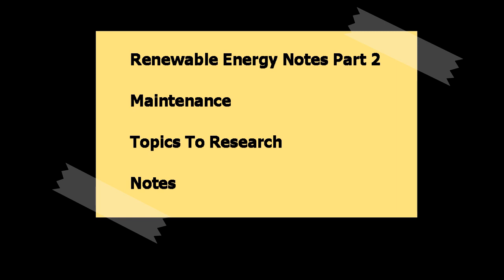Going over some tests that you need to do when you have a solar system or when you're installing a solar system. There's 3 tests that I'm just going to list that you may need to look up in your spare time, just to make yourself more familiar with the terminologies and what they mean. Here we are with the first one, continuity test, and that is to make sure that there's no breakages in the wires. Polarity test and insulation resistance test.